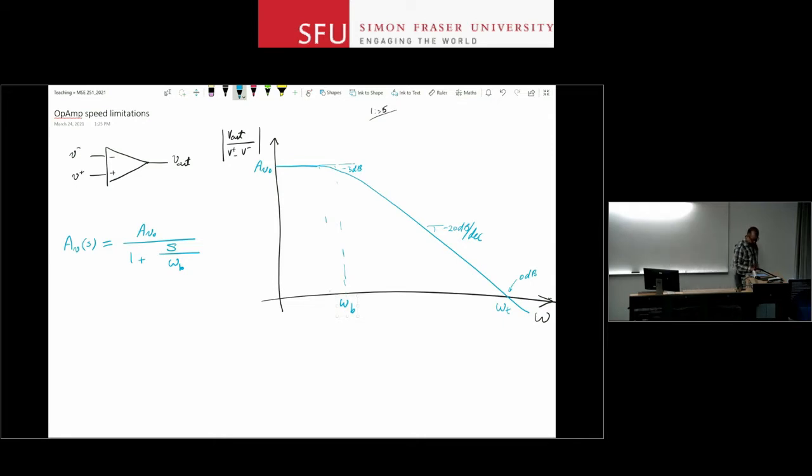Okay, so this is how I can model that, right? Knowing that I can look at the op-amps in most situations, they're designed to behave like a single pole system. The transfer function can be written as this, right? So I know AV naught is large.